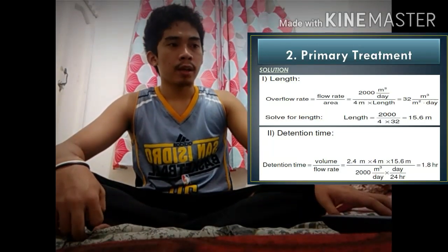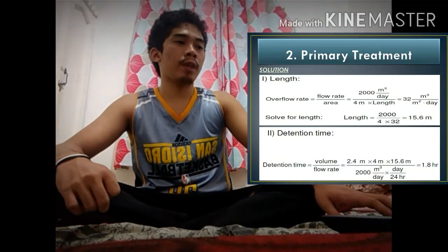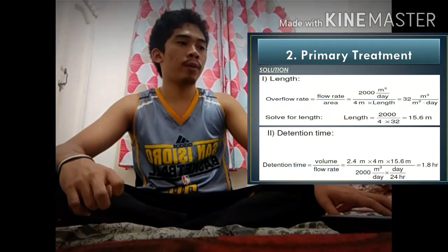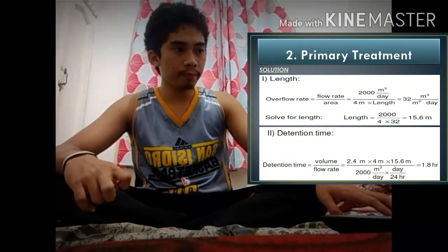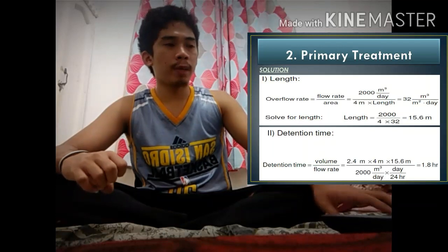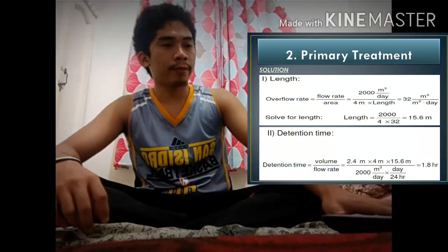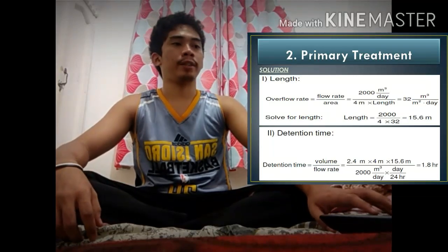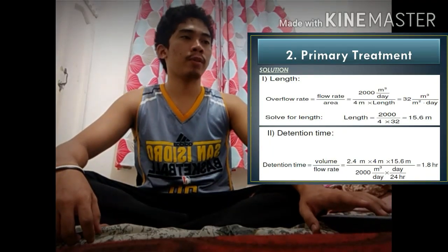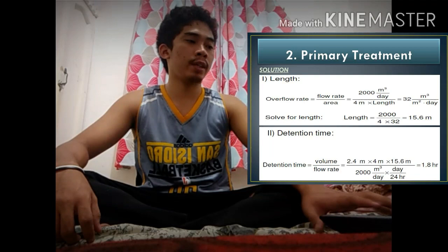In detention time, we know that detention time is equal to volume over flow rate. Just plug in the given data and we come to an answer of 1.8 hours. That is the detention time of the given example.